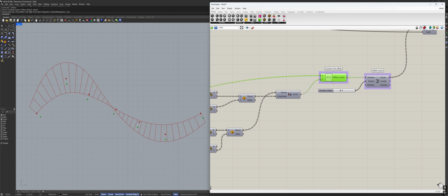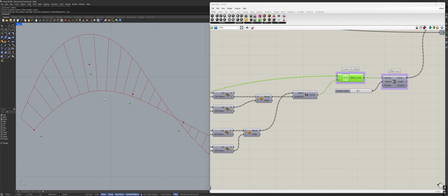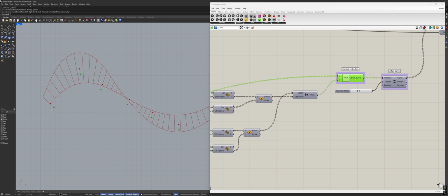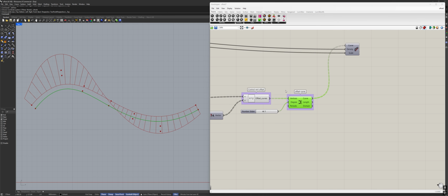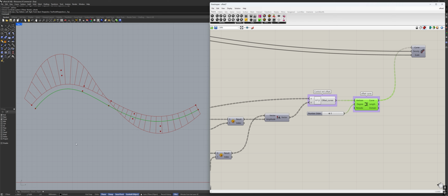So here you're going to see the offset of these points in the normal direction relative to the curve. So what Alias will do is create these offsets on these points, here, here, here, here. And then it will reconstruct a new NURBS curve with the same degree as the original. Of course, it can't do it any other way. So if that was a 3-degree curve, it means it has 4 control vertices. So 3-degree curve, 4 control vertices, 0, 1, 2, 3, and then it gives you the curve.